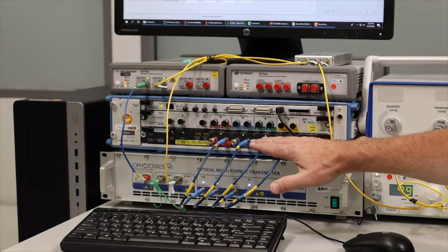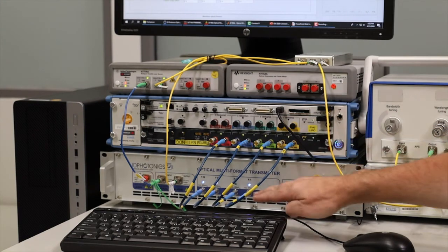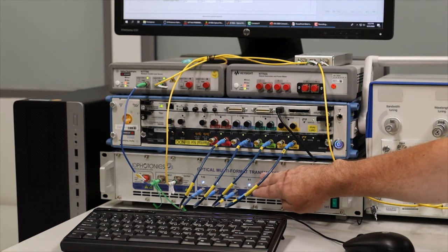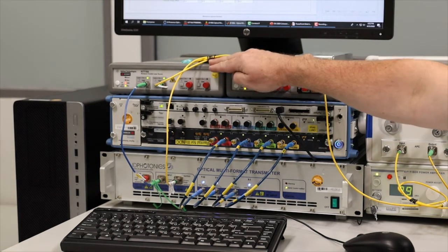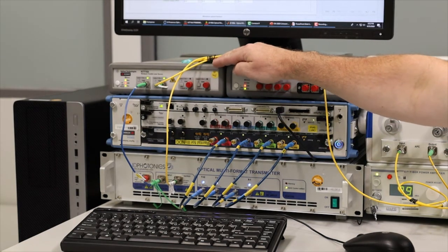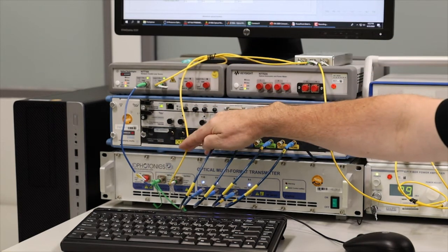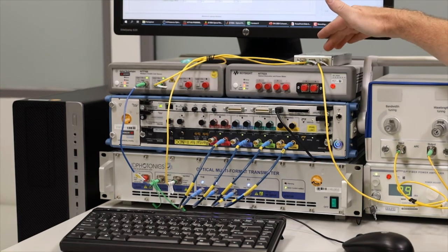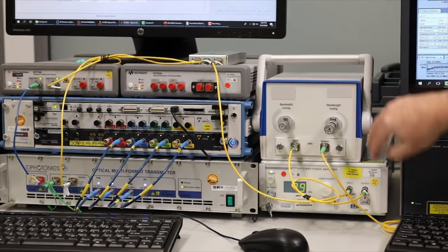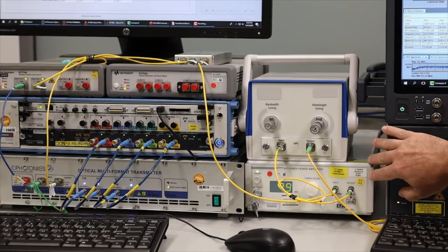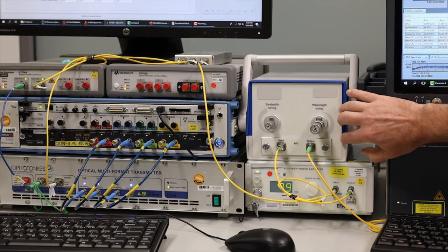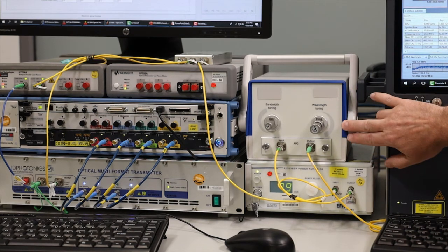The electrical IQ signals now leave the AWG into the optical multi-format transmitter, a modulator provided by the company IDPhotonics. The carrier is generated with this 4-channel tunable laser source. The signal leaves the modulator on this yellow fiber. Some signal conditioning is going on. I have a coupler, a filter, and an amplifier. They are used to amplify the signal in the case of the amplifier and get rid of some broadband noise in the case of the filter.